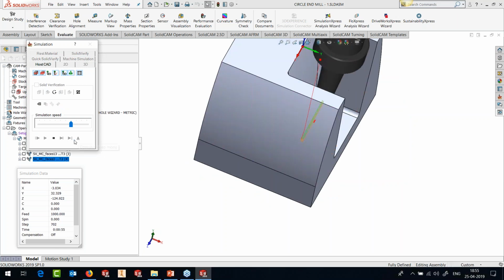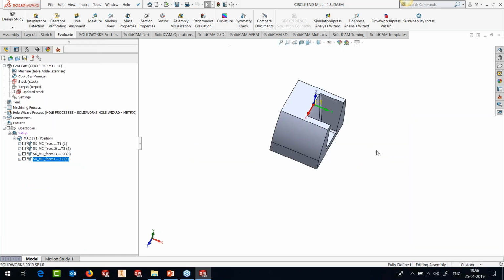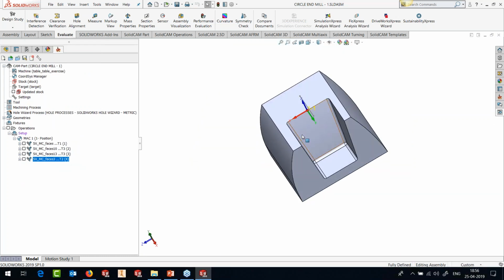So that's how it generates the machining. So we can now use any of the barrel shape tools, either it's a barrel shape, oval form, taper form, or lens shape. You can use any one of them. By the way, we also support a double barrel, where it has got a large radius on the side of the flank and also a large radius.